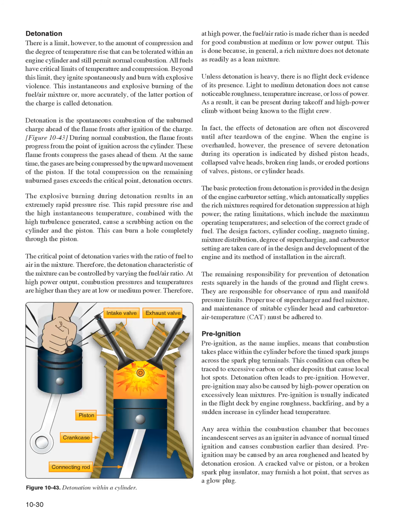Detonation. There is a limit, however, to the amount of compression and the degree of temperature rise that can be tolerated within an engine's cylinder and still permit normal combustion. All fuels have critical limits of temperature and compression. Beyond this limit, they ignite spontaneously and burn with explosive violence. This instantaneous and explosive burning of the fuel/air mixture, or, more accurately, of the latter portion of the charge, is called detonation. Detonation is the spontaneous combustion of the unburned charge ahead of the flame fronts after ignition of the charge.